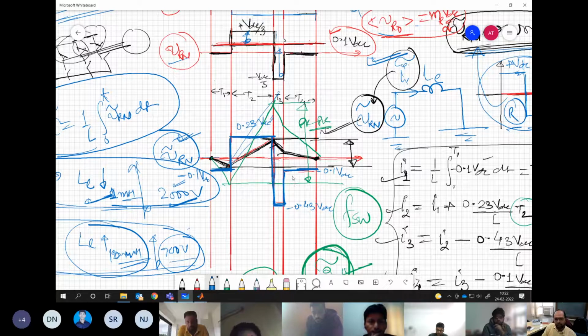When I say ripple voltage, the average value of this voltage, which you are feeding into the system, is 0. You have subtracted the average value, so whatever is remaining is only the ripple, or you can say error, into the system. And because this has no average value, the current which it will generate also cannot have any average value. We are talking about a linear system. So the ripple current can be drawn corresponding to this voltage on the basis of this equivalent model we discussed earlier.